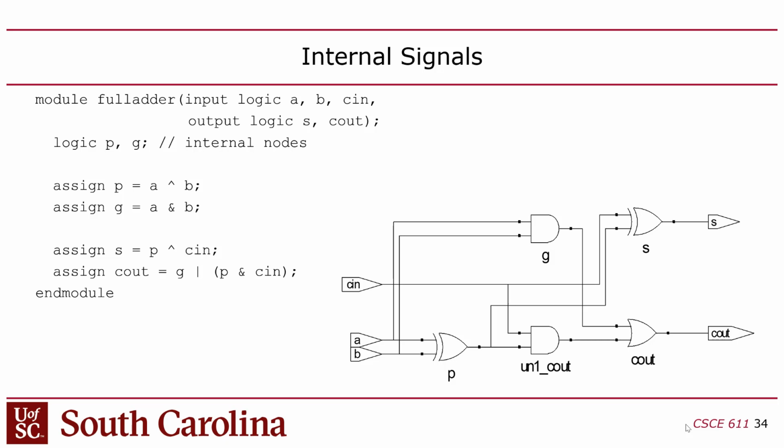We used to use that as a trick to find out how fast a new process was. Say, oh, we got a new technology library for AMI quarter micron. Let's see how fast it is. Ring oscillator, go. And we'd see how fast it would oscillate. I don't know about FPGAs. That's a good question. But even if you did do that, you'd have to tune it for the FPGA technology. So it wouldn't be something like, I want you to wait for 5 nanoseconds, so I'll put in a 7-stage ring oscillator. You'd have to test it. But I don't even know if that would synthesize. That's a good question. I should try that. It's a good idea.